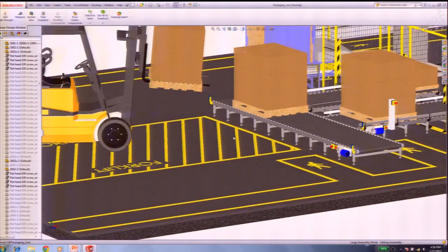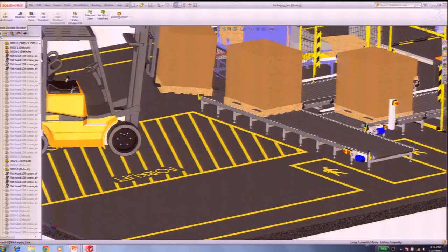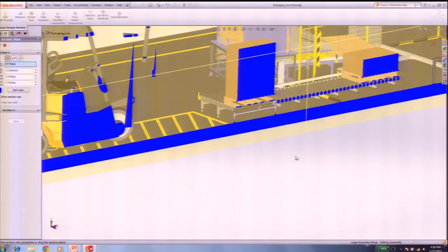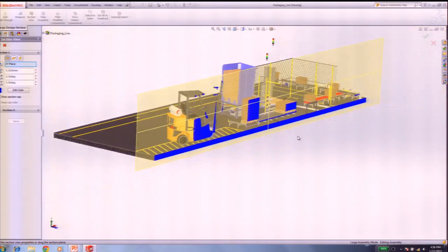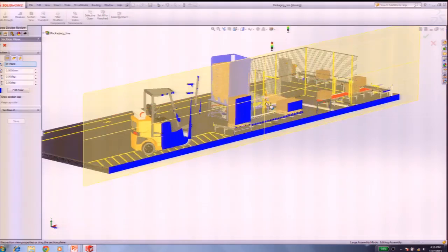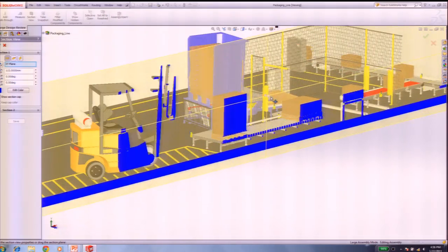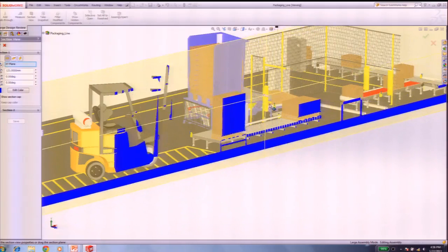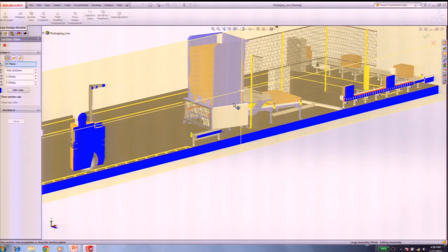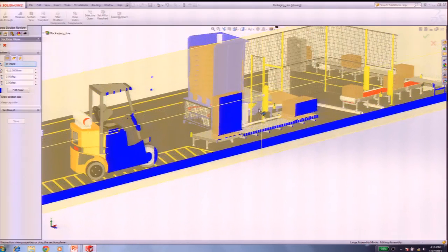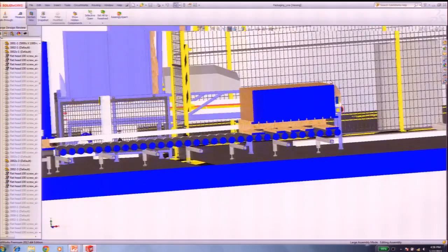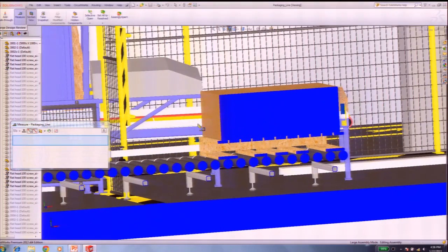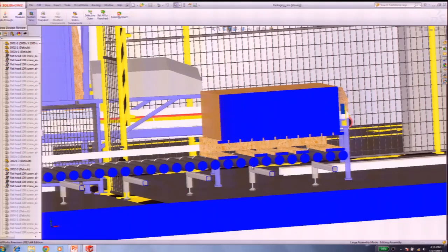So then, carrying it just a little bit further forward, I can then just insert a section. And here I've got my sections that I'm very familiar with, because it's just like standard SolidWorks design mode. And here I can drag my sections to go through and check out particular areas. And here, just simply accept a section, and then I can go in and repeat the process, measuring things, for example, here in the section mode.